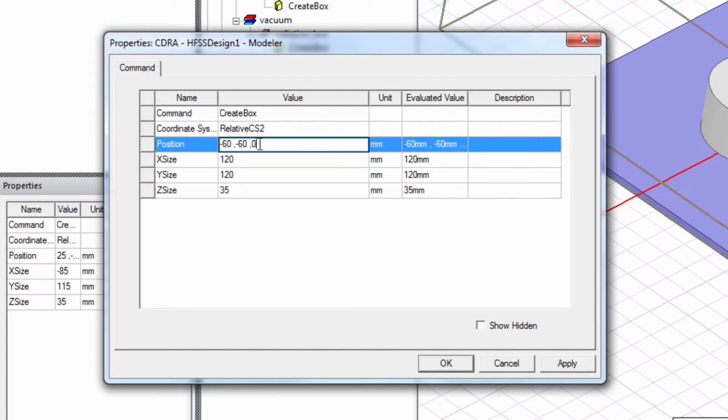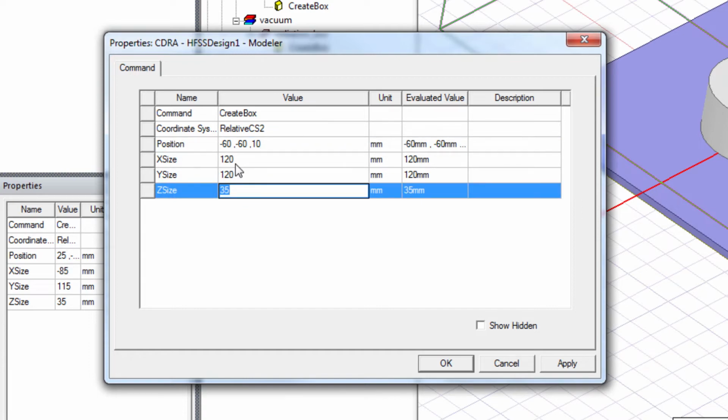So we can define less area below the substrate for the radiation box. You can define, like, let's say 10, but in the top direction the maximum amount of radiation is going to happen, so you're going to make sure that you have enough room in the top. So let's take it 50.